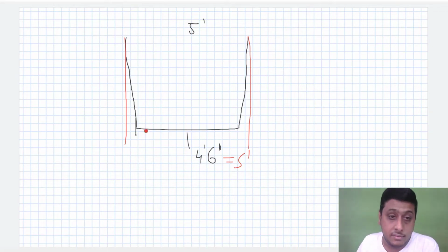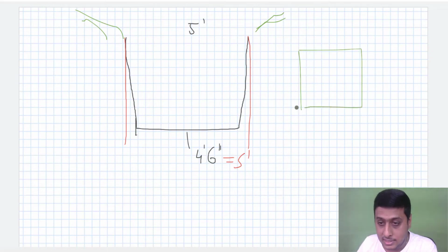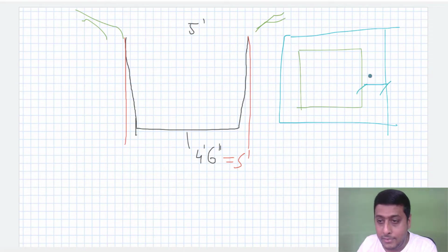And the third one: when we excavate the earth, the soil that has been lumped next to the pit has to be cleared minimum 1 foot away from the pit. For example, if the pit is a rectangle or a square, the loose soil should be lumped a minimum of 1 foot away from the excavated earth.